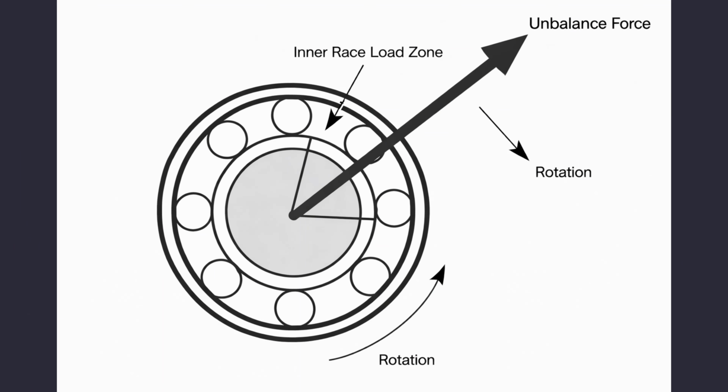Why we typically and more significantly look at unbalance is that this is one great value of force which is rotating as a function of 1 into RPM and has a direction which is directly on the bearing. So even looking at large bearings that support these kinds of rotating equipment, a continued load of centrifugal force with a large amount of force is sure to deplete the quality of the bearing and overall end up in a lowering of the life itself.